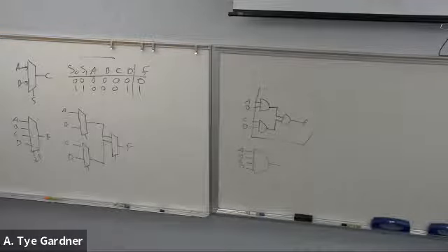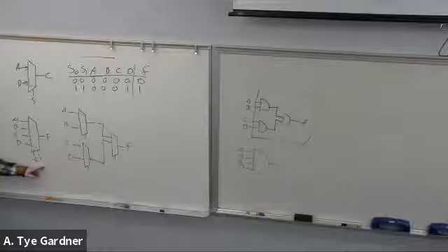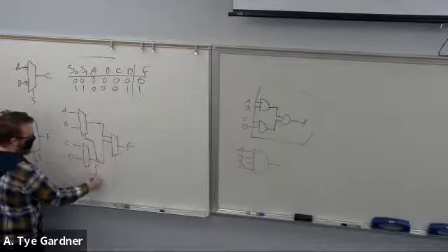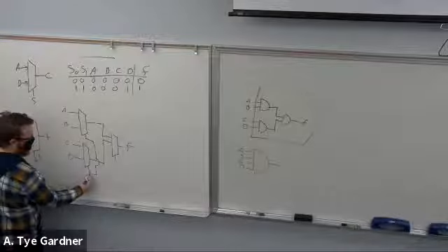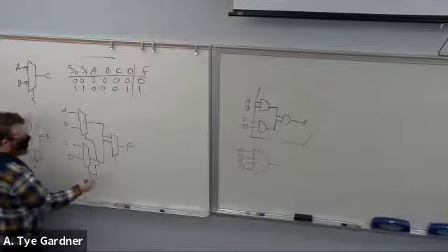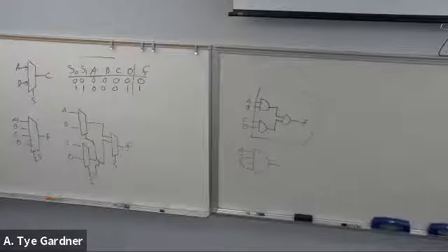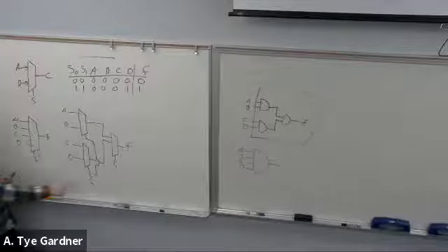What do we do with the selects? We know we need a select 0 and select 1. Where do they go? How do I order these in order to make them work? You tie the two selects from the first pair of gates to one of them, probably it's S0, and then this one S1. So, absolutely the right idea. Let's make sure it works.